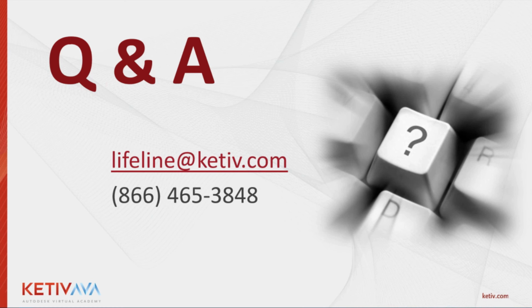For sure. Let's see what we have here. And Daniel asks, how do you create different views on a 3D PDF? If I remember correctly, those are from the views that you create within the assembly. Exactly. Yes, exactly. You can have different representations if you want in your model, and you just insert them into the PDF. But also, it's important to note that you can generate your own template. The template that I use is the one that comes with Inventor. But if you have something like an Acrobat Publisher, you can generate your own template to reuse.